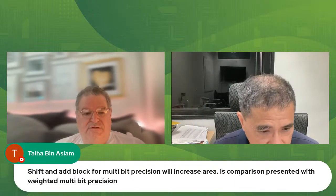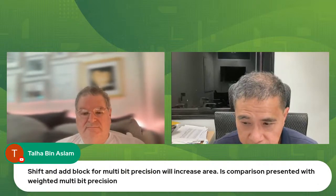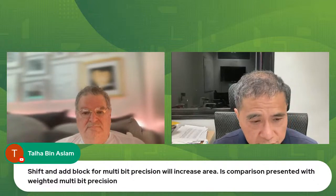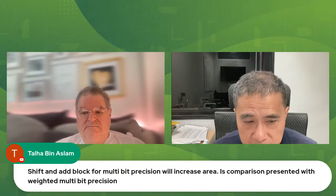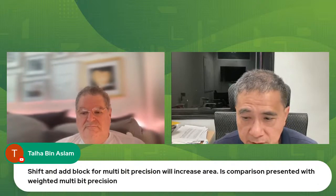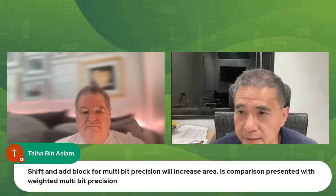Regarding the shift and add block for multi-bit weights, does it increase area? For our design with 4-bit weight and 4-bit input, we don't need a separate shift and add block. Only when we do 8-bit weight. So the compression is also handled together with the weighted multi-bit precision already.